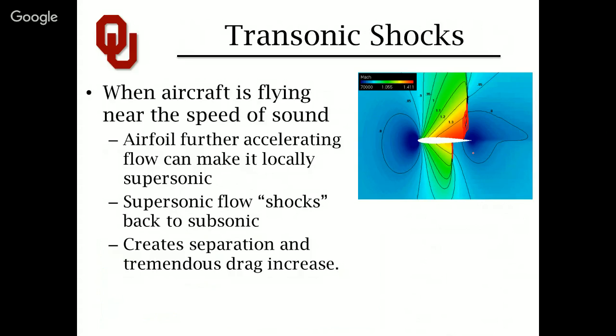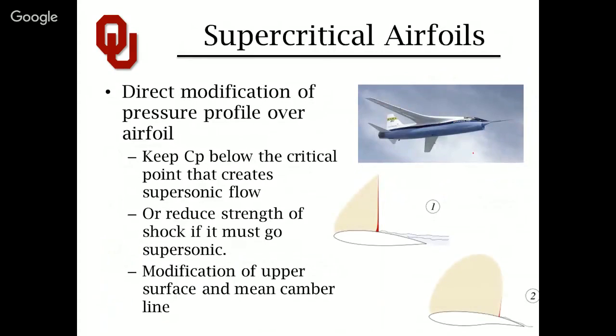First of all, you generate supersonic drag because of the presence of that shock. Secondly, as depicted here in this image, it generally will separate the boundary layer. Right where the supersonic shock happens, due to this very classically designed, almost NACA 4-digit symmetric foil shape, you get a very, very strong shock wave right there, about 50% chord.